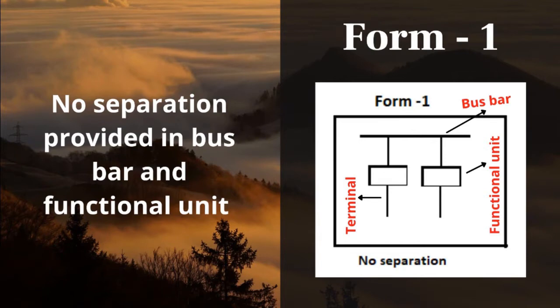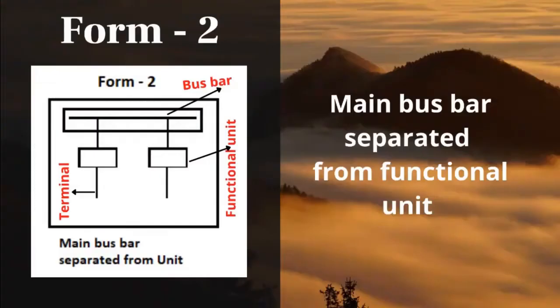Form 1: no separation provided between bus bar and functional unit. Form 2: main bus bars separated from the functional unit.